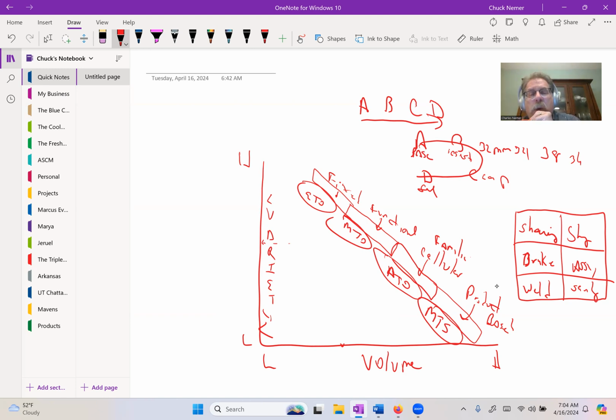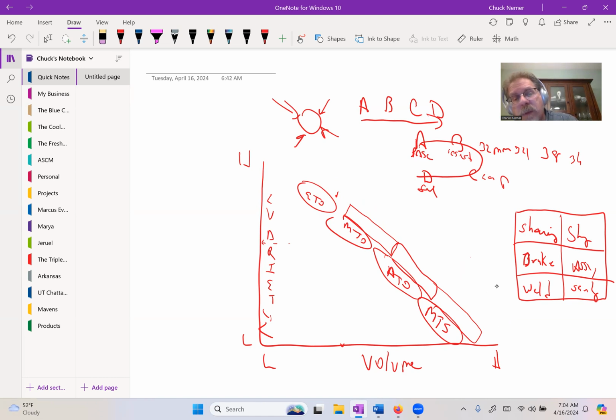And then finally, engineer to order, fixed position. What we've got there is people come to the work center where we're putting together this packaging system that I was talking about. So that's the 4 areas that are going on here: fixed, functional, cellular, product based. Okay. So wrapped around that, then, we'll go a little bit further. The engineer to order, from a manufacturing process type, tends to be more project based.